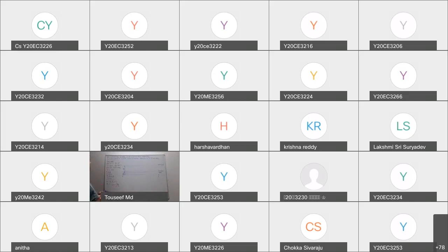Next, we know the front view is equal to 65. I take any point on the locus of A dash, somewhere right here, and this becomes my A dash. I know A dash B dash is equal to 65, and I know the locus of B dash. With A dash as center and 65 as radius, draw an arc to obtain B dash.